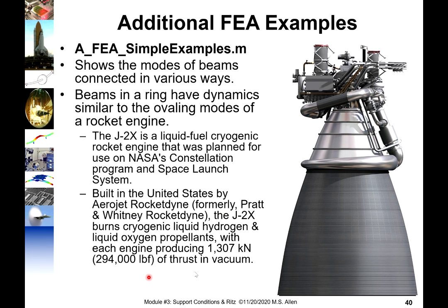Well, all kinds of rocket engines such as this can have a problem with lateral forces being exerted by the flow. So the flow coming out of the engine can separate so that you get a higher pressure from the outside atmosphere coming in, or a lower pressure depending on what's happening. And that flow separation can actually be variable with time.